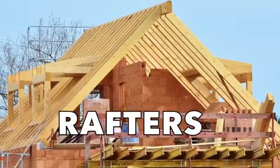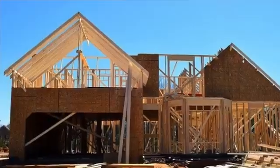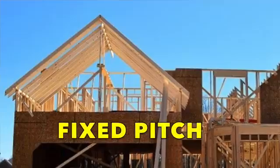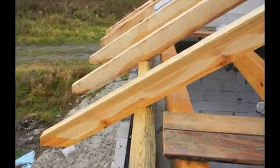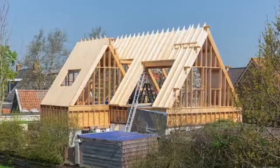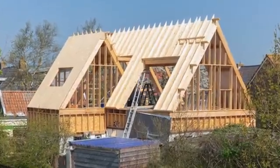Things only get different again when you finally get to the roof. Roof framing is a complex topic because things stop moving in 2 dimensions and they start converging in 3 dimensions. In traditional framing, roofs are made up of rafters. Rafters are a lot like floor joists, except they're set diagonally at a fixed pitch. At the bottom, rafters sometimes sit on the top plate of the wall below. Other times, they sit on yet another floor structure in the attic.